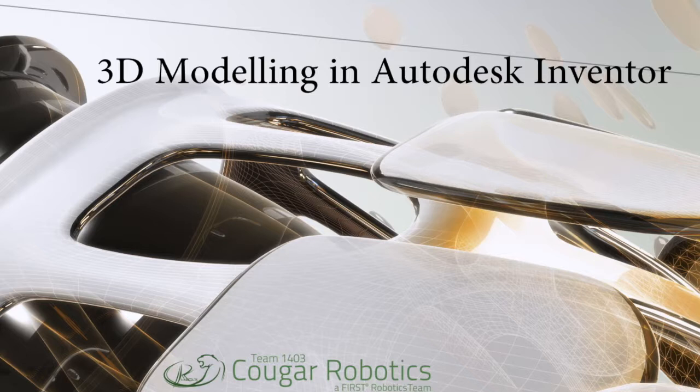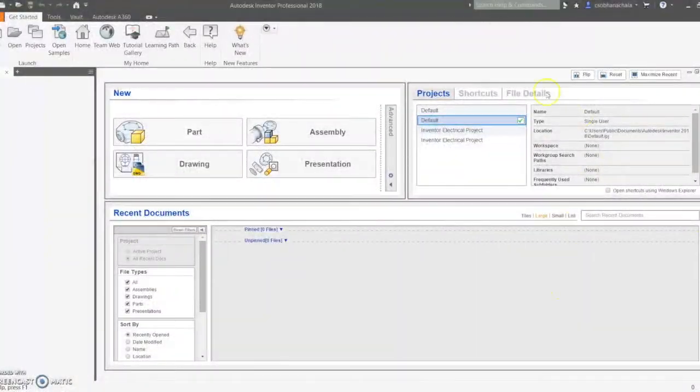When you open up this program, which is called Autodesk Inventor, you'll be greeted with this screen. Here you have your recent documents, your projects, and the tab we're concerned with, the New tab. Under the New tab, click the Part button.